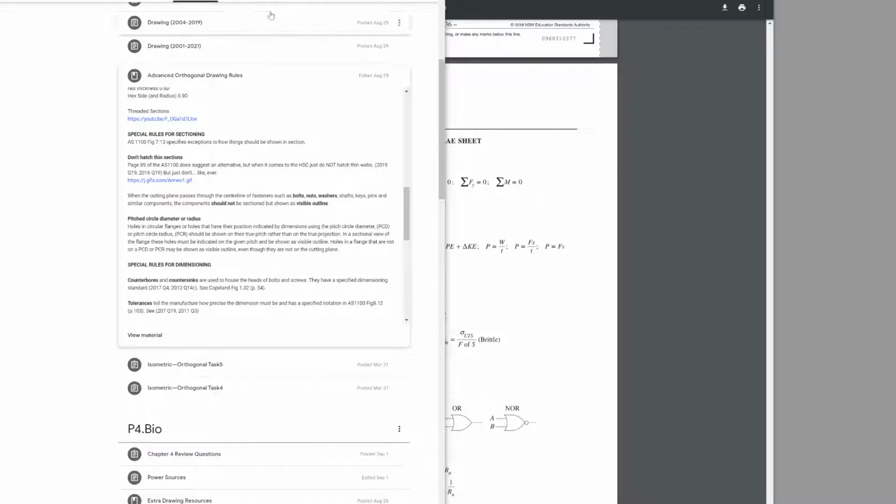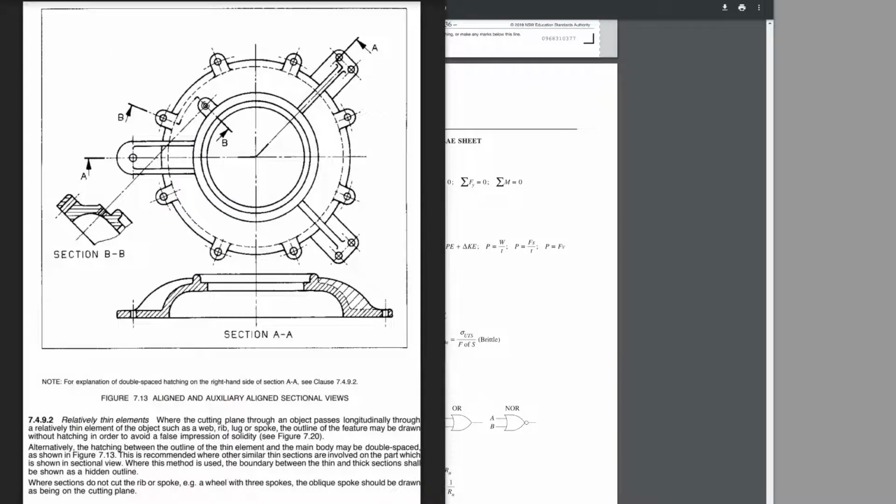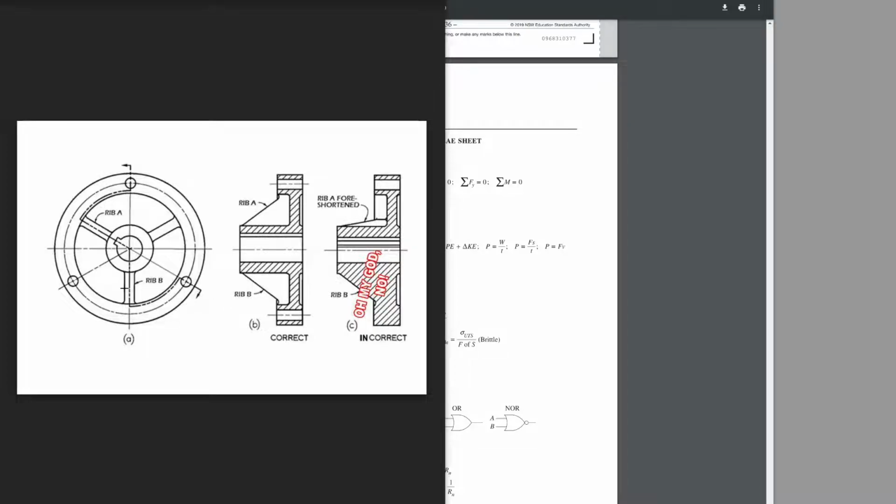Okay. So if I have this picture and I also have this picture, here we have a very similar looking shape and we can see that we've moved our section line through all of the interesting stuff. Even though we've got 3 holes and 3 stiffeners, we rotate it so it looks like there's 2 holes and 2 stiffeners and we show them symmetrically.